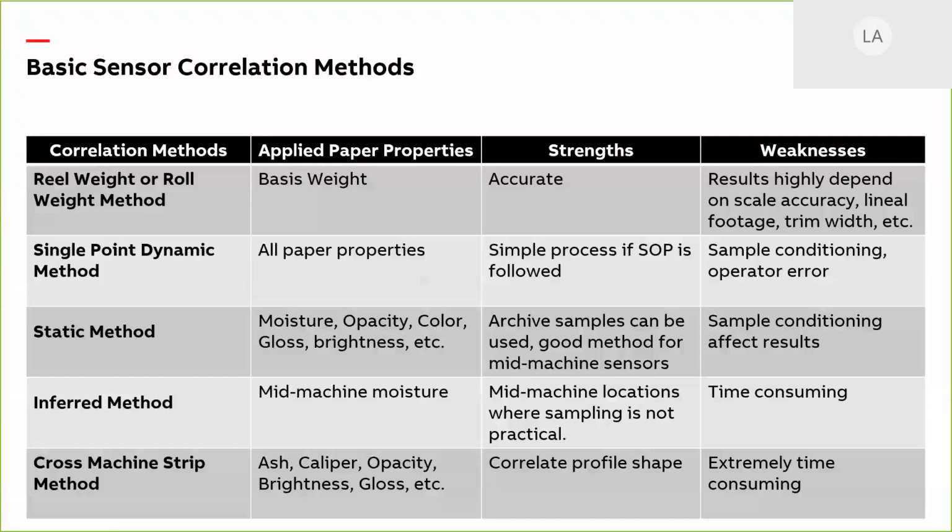I've seen a lot of paper testers who don't follow the standard operating procedure. I'll talk a little more about that later. What are the discrepancies, where does the source of the error come from, and also, are they validating the results? So if they take 3 samples from a reel, are they just simply averaging them? Do they even look at the data?